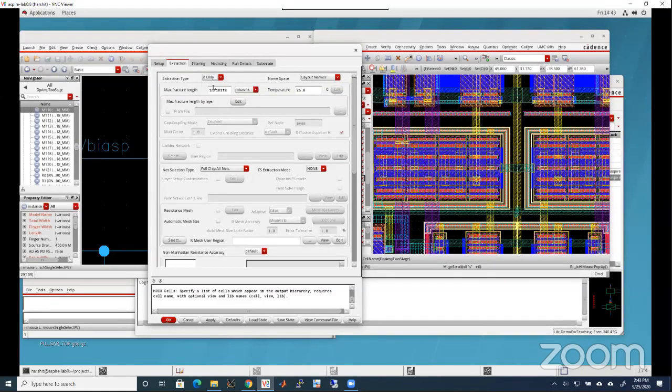R only gives you a little more than a moderate size netlist. Okay. RC gives you the largest netlist. Now, what are the repercussions? The largest netlist means more simulation time, more nets, and more variables to be saved. It takes a huge amount of disk space, so we have to be optimal in terms of doing that. Am I clear?